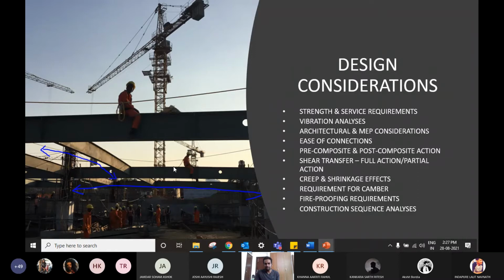When you measure the top of your middle portion of the beam and the top of the end portion, there's a difference of 20 or 25 mm. So that's what you call cambering. You provide the bend in the opposite direction so that when the building gets loaded, it's going to negate that camber and needs to put in more effort to make it deflect downwards, right?